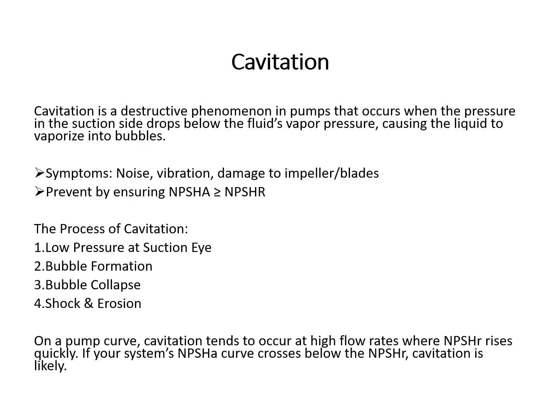Now let's talk about the cavitation phenomenon. Cavitation is a silent killer. It sounds like gravel in your pump and leaves pits on your impeller. We will explore why it happens, how to hear and see it, and what system tweaks help eliminate it. So it is a destructive phenomenon.